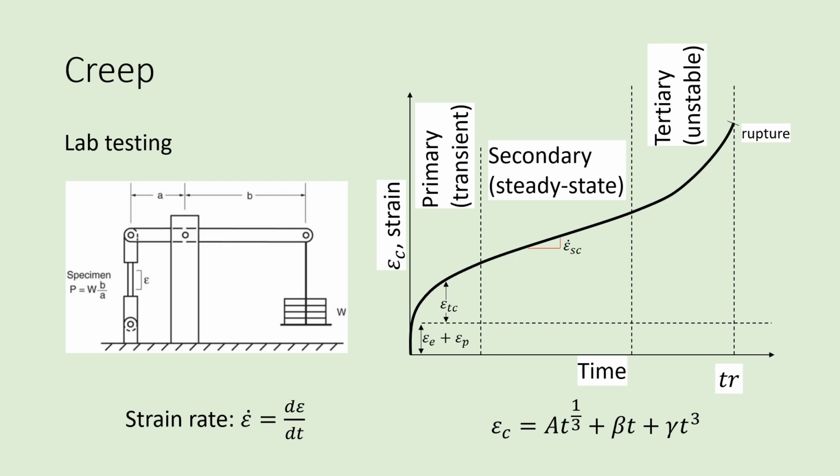During this primary stage of the strain time curve, transient creep is occurring when a force or stress is instantaneously applied to the object. This leads to instantaneous elastic and/or elastic and plastic strain, which is represented by that horizontal dotted line. Due to the nearly instantaneous deformations, the strain rate, or change of strain with respect to time, is extremely high at this point. As time progresses, strain accumulates through transient creep, and the strain rate gradually decreases until it approaches a constant slope, at which point stage 1 ends.